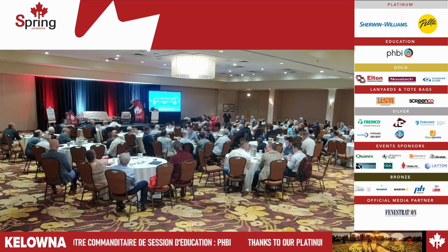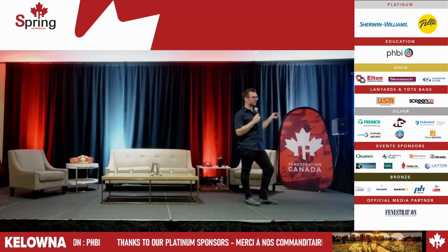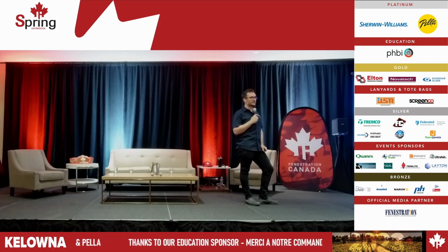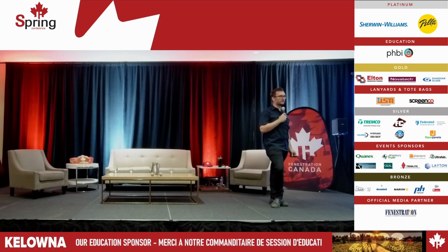Yeah, that's a good point there, Terry. And I'll just touch on what we're seeing on the Part 3 side too, is we're getting the building envelope consultants specing this exterior insulation. We're getting these effective R25, R28 walls, and we're still installing a metric U value of like 1.6 for double glazed windows. And your weakest link is your windows. So that education has to be getting back to the builders and providing those cost upgrades, because when we run the costing analysis, investing in windows is considerably a factor in getting to your step code metrics cost effectively.